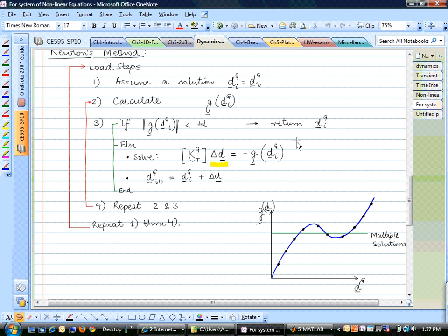But there's also a different type of nonlinear step in Abaqus that they call static Riks. And the Riks method takes these types of small increments. For example, this is the displacement versus residual, or displacement versus load curve.